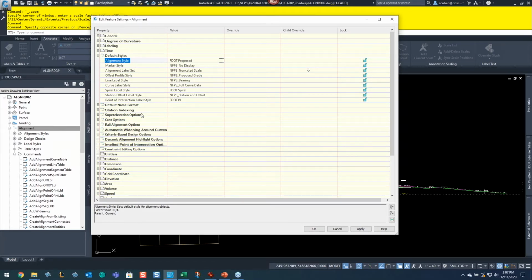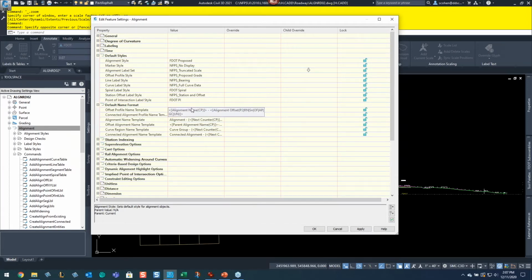Okay. Same thing with the additional stuff here. Same thing with the names. If you don't want the name to be alignment name, whatever, you could call it something else. Sometimes I'll put in there "rename me" with exclamation points. That way I remember to actually give it a name, or for other users at the company to make sure they give it a name. Because sometimes people just click OK and before you know it, you have 5 alignments named alignment 1, alignment 2, alignment 3, and it looks kind of silly.